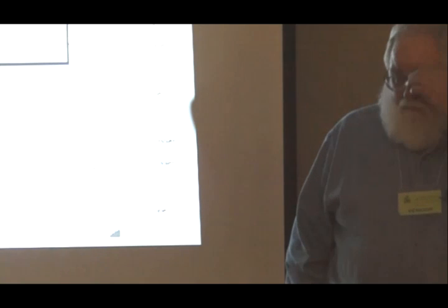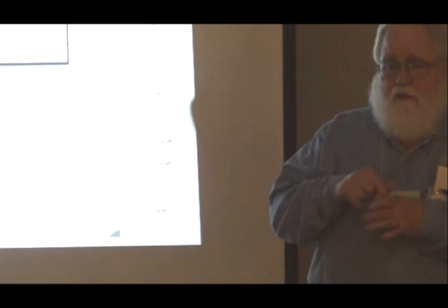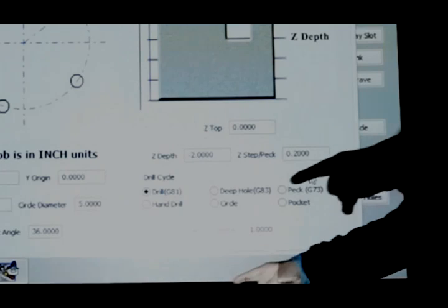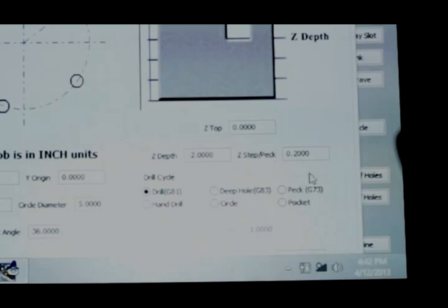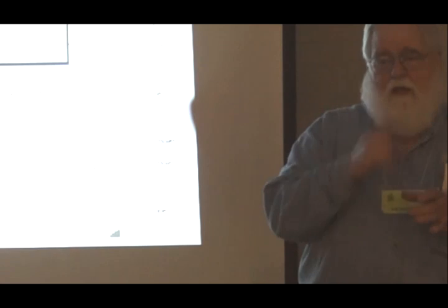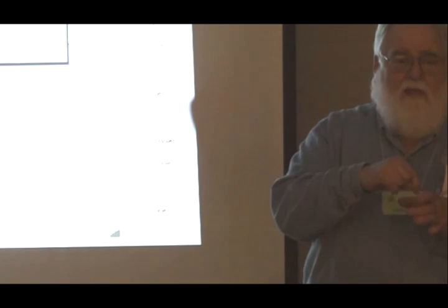And then we said, well, what if we want to do a counterbore around something? I want to make a counterbore around the bolt circle. So we have a circle cut and a pocket cut. Now a circle cut is there because let's say that I've done a half-inch hole and I've still got this half-inch tool and I want to make a 3/4 inch pocket around that.